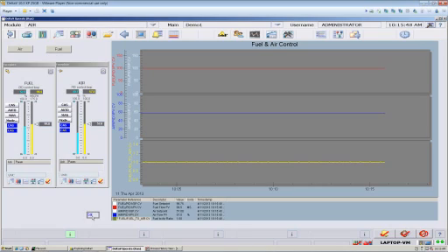It's kind of a good example of checking your entries before you hit enter. I just about hit 0.59% there, but I saw my mistake and corrected it. So here is a 2% set point change. You can see the white fuel set point increase a little bit here, the blue air set point increase a little bit there, and the fuel and air are both going up, meeting it.